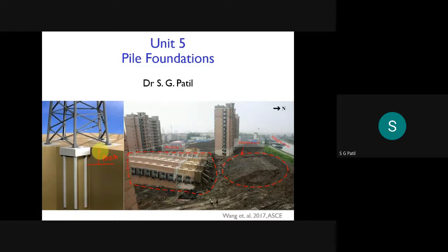If you are building some small residential building, then that solution is good, because going for a pile foundation is a very costly affair. It requires a lot of money. It is a very specialized type of foundation, so even the contractor should have good experience in the design and the pile installations. The cost involved in a pile foundation is a little bit higher than for shallow foundations.